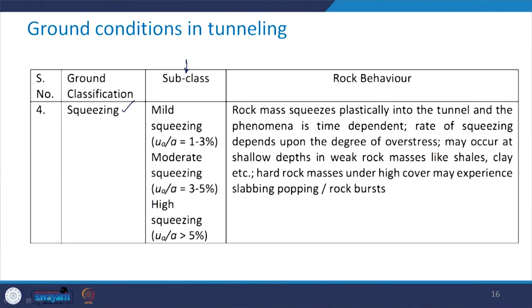The squeezing rock mass is plastic. It squeezes plastically into the tunnel, and this phenomenon is time dependent. The rate of squeezing depends upon the degree of overstress. It may occur at shallow depths in weak rock masses such as shales and clays.